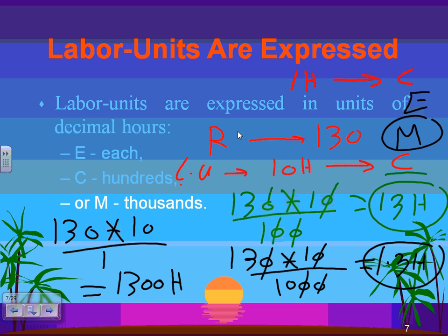I need 9.6 hours for every M. So you measure the cable, multiply by 9.6 for MC 14.2, divide by 1,000, and that will get you how long it will take to install that section of the cable, based on skilled, qualified, motivated electricians working under normal conditions with the proper tools.